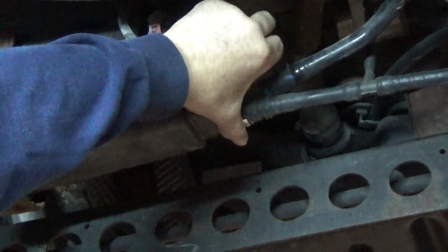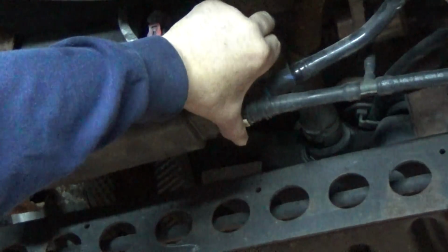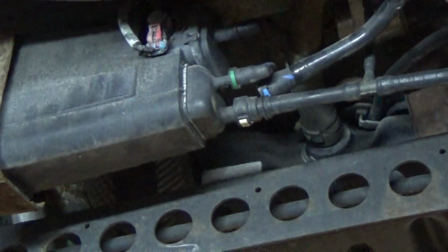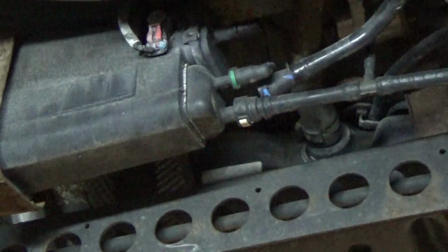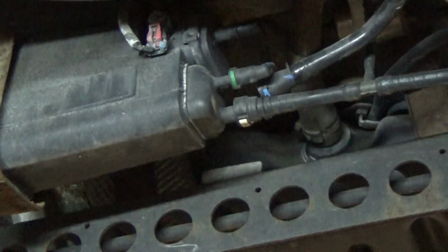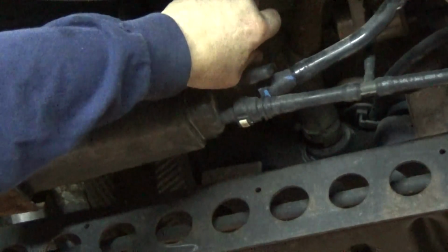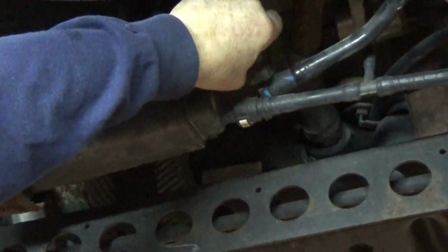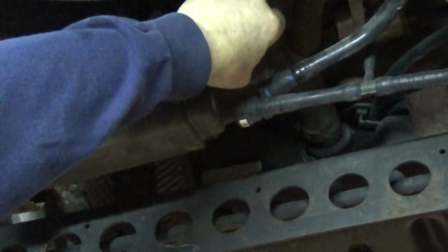Right now we're sitting at 10.21 millimeter mercury. There's 10.03. If I take my finger off, 985, 1003, it's kind of flashing back and forth. It's really not changing the speed that it bleeds the vacuum off at. Again, if the vent valve was leaking, this is all we'd need to do to manipulate the system. Just block it off with my finger.